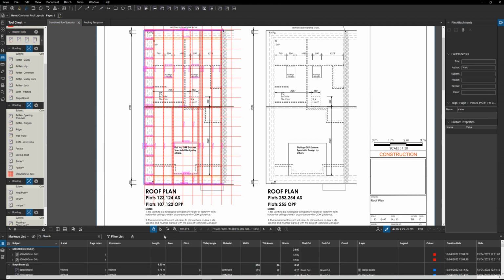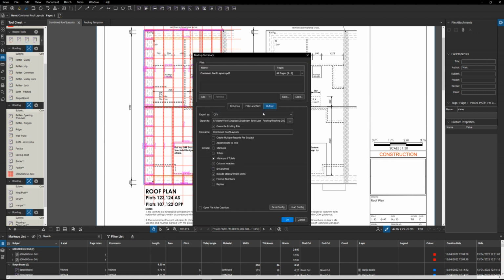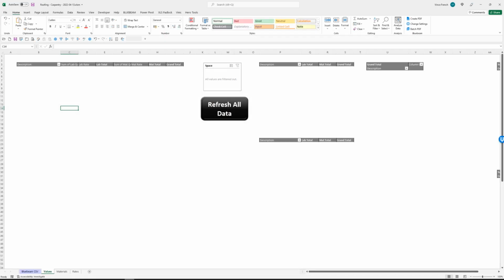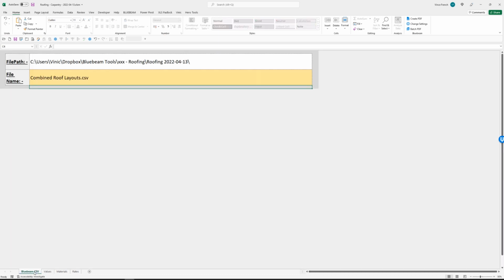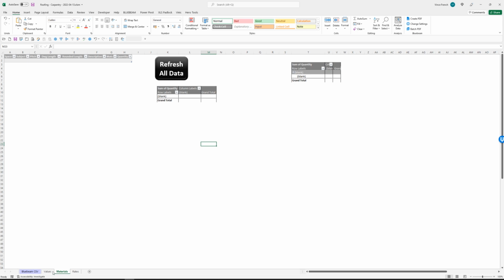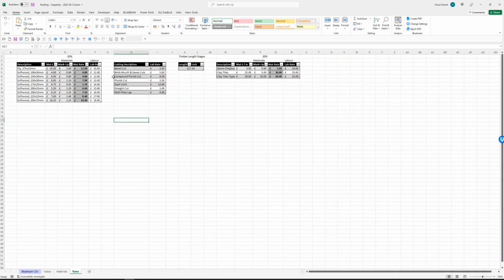And then I will export my measures, CSV summary. This is already set up to where I want it to go. I'll press OK. I believe that's done. Then I'll load up my spreadsheet, which refers to my CSV file. At the moment, no details in here for the materials. I've got some details for the rates and the cuts. What I haven't got is the right timber sizes for this.